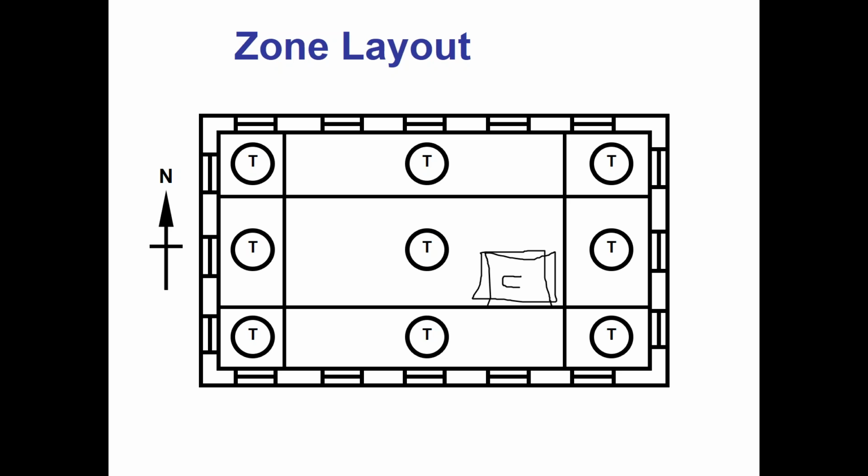And then, of course, you have to still balance the fan on the air handler itself. You have to balance the return side. You have to balance the outside air economizer or minimum ventilation position on there that you would have to do as well. So there's going to be a lot of steps on there. Some of them you have to do on a constant volume system. Some of them are unique to VAV. But balancing is actually a pretty big deal on these systems. Actually, it's a pretty big deal on all systems and something that we can all probably improve upon.